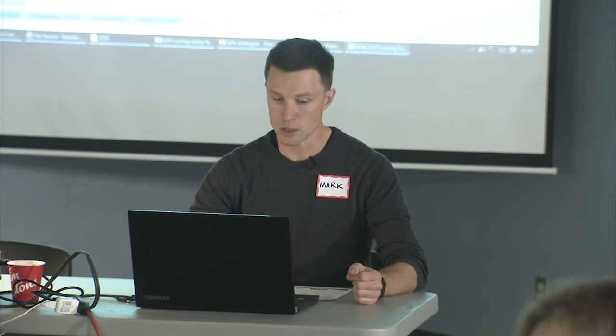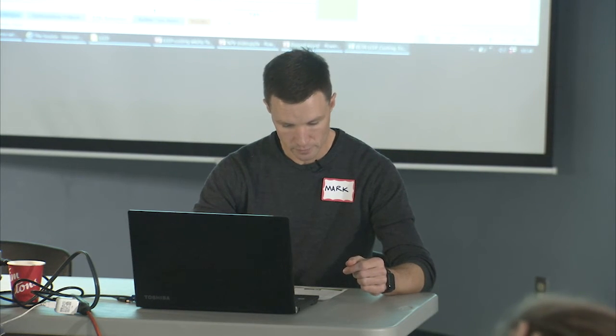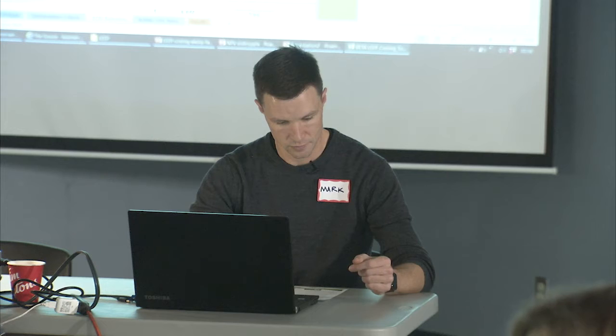Okay, so let's move on to the next step. Let's look at the impacts of allowing for tighter houses, for improved airtightness. So let's go back to our ECM selection. We'll go to our ECM table and scroll down to the airtightness section. Without changing the heat pumps, which we've still set to no, we'll change the airtightness options all to yes. So we'll allow 1 air change per hour, and we'll allow 0.6. Once you've got those set up, you can go back and click Optimize again, and we'll see what happens this time.